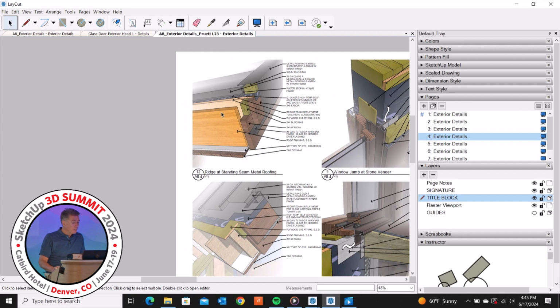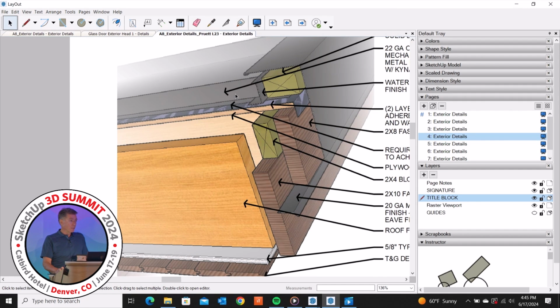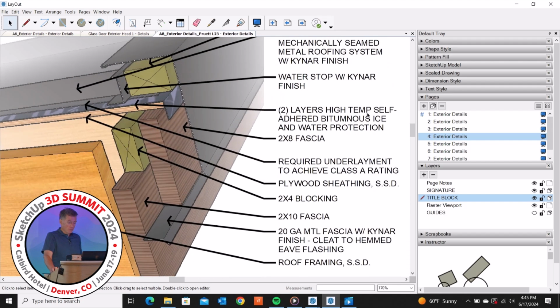No ice damming on all that built-up insulation? No, we still get ice damming. It does happen. We do put 2 layers of ice and water shield down, and the 2 layers is required on anything that has a pitch of less than 2 in 12. And so you can see on that note, it'll say 2 layers.